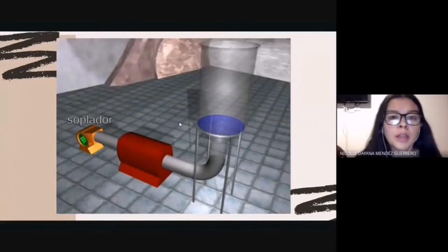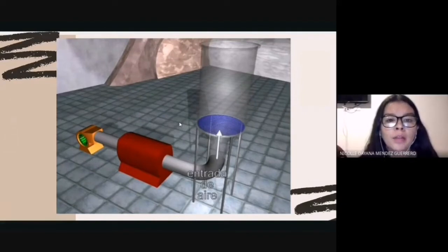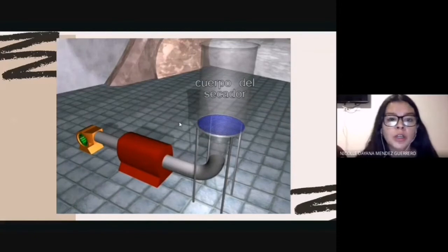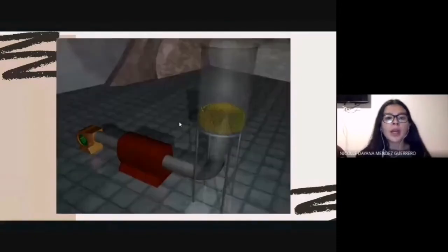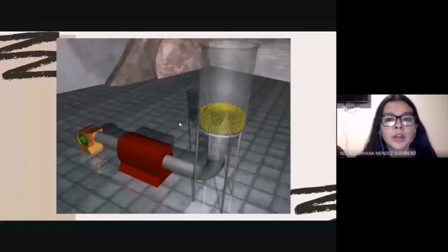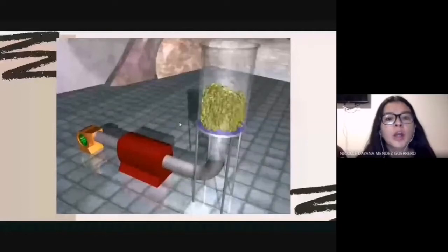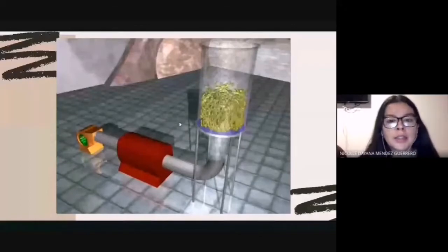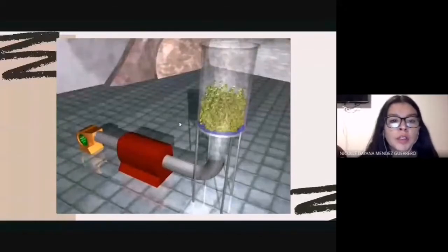Operation: the suspended material is continuously fed to the bed chamber, which is filled with ceramic spheres with a diameter of 1 to 3 millimeters. As soon as the material is introduced into the chamber, it is rapidly dried by the combination of conduction heat from the heated ceramic spheres and by the convection heat of the hot fluidizing air. The wet material will adhere to the ceramic spheres that flow in the fluidized bed and will instantly become dry. During the flow, the ceramic spheres are fluidized and collide with each other, separating the dry product from their surface.